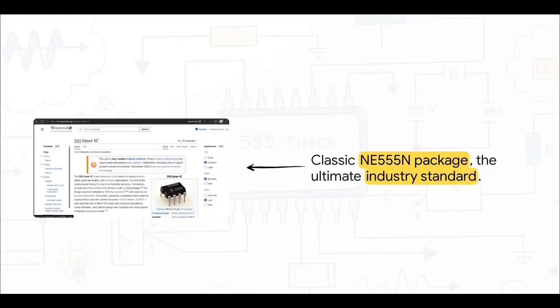So here it is in that classic 8-pin package. Rumor has it, it famously got its 555 name from its internal architecture, which features 3 5-kilo-ohm resistors. This thing is incredibly versatile and super reliable, mainly because it handles a really wide voltage range, from 4.5 up to 15 volts. That makes it totally perfect for simple, small battery projects or massive, complex industrial systems alike.